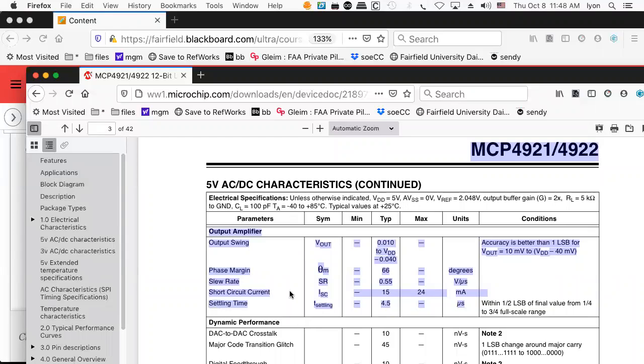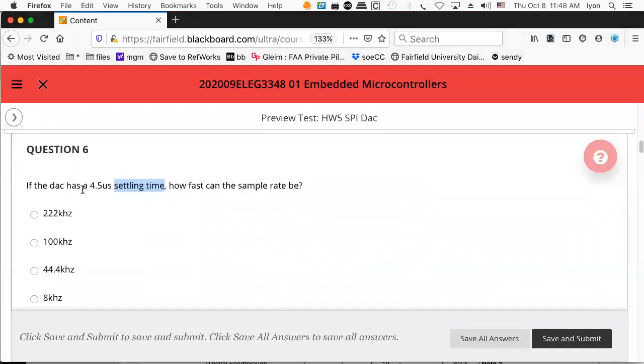So basically, you're going to have 12 bits of signal to noise ratio, which is probably 6 times 12 plus 3 dB. That's about 75 dB of signal to noise ratio maximum on your output, assuming you use all 12 bits. So that's consistent with the DAC that we're using. Don't know if you're going to actually achieve that with what we're doing, but there it is. That's in theory the best you could do.